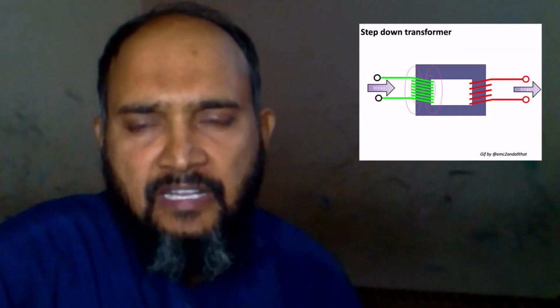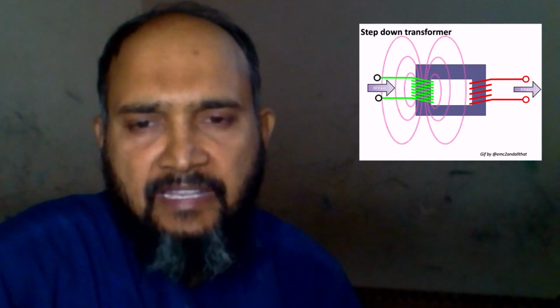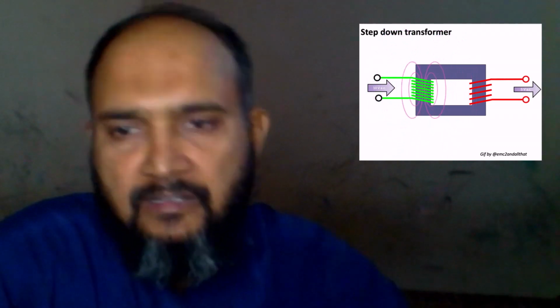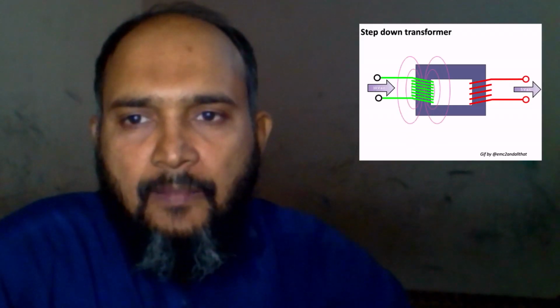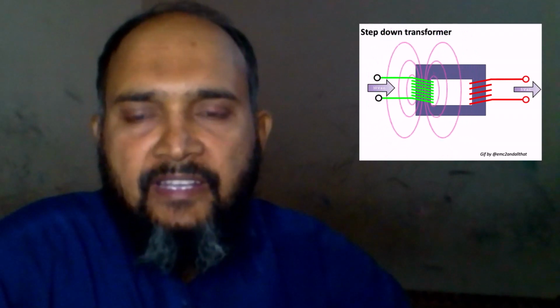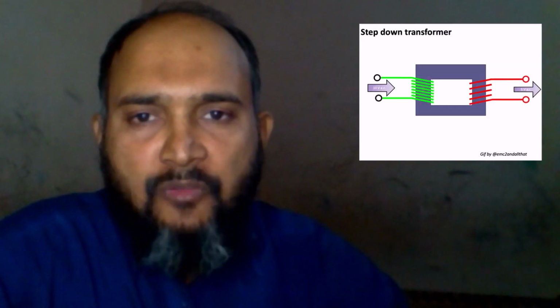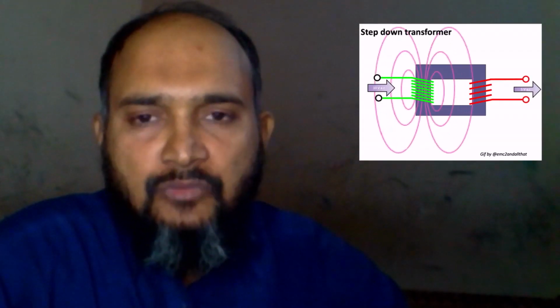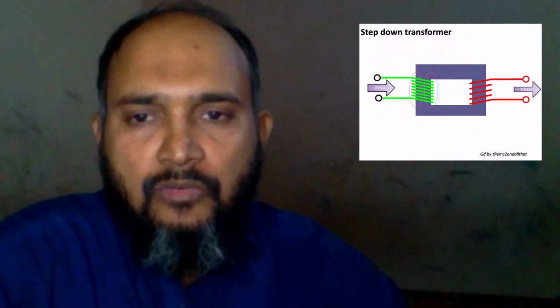This relationship has a very close mechanical analogy. Use torque and speed to represent voltage and current respectively. If the winding ratio is reversed so that the primary coil has fewer turns than the secondary coil, the transformer steps up the voltage from the source level to a higher level at the load.